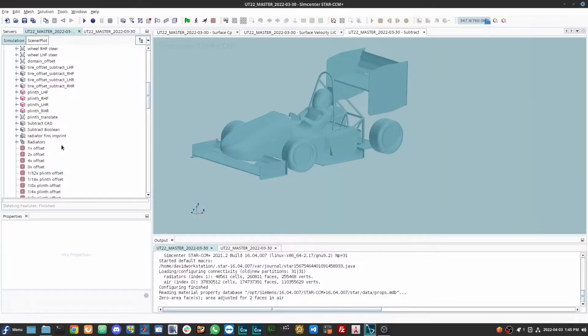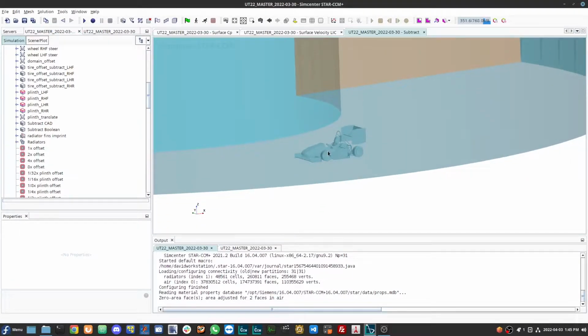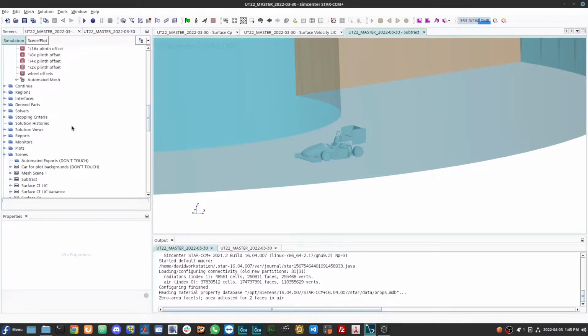Before I go on to post-processing, one thing that troubles a lot of people is oscillating results. Now, when you have separated flows behind things like tires or on your wings or in a heavy side slip, you're going to have some separated flows, and those are likely going to present issues with convergence and getting a stable, dead-set value of forces and moments. Now, there are 2 ways we can deal with that, depending on what you're trying to average.